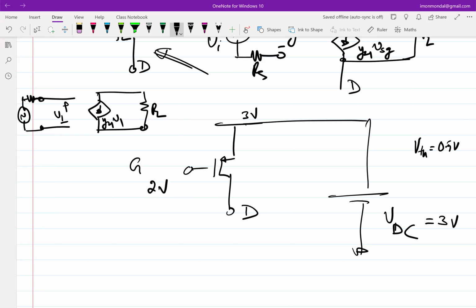Okay, so fine. So now with this, we only know that the transistor is on. We don't yet know if the transistor is in saturation, right? So what determines if the transistor will be in saturation or not? Yeah, the drain voltage, because the source is constant, right? So we have fixed the source, we have fixed the gate. Basically, the drain voltage will determine. So now, can you tell me the minimum or maximum drain voltage?